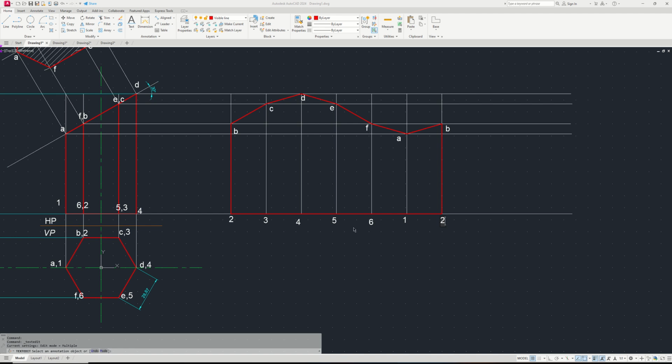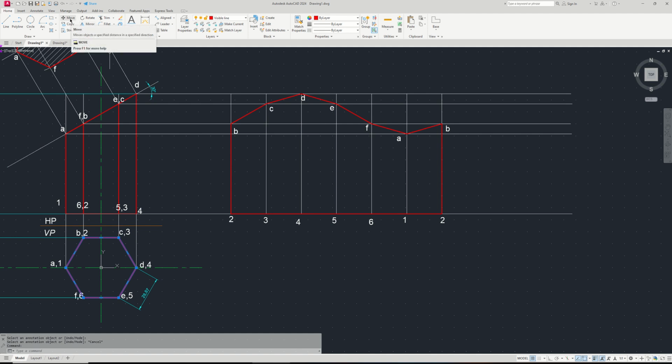Then I also made a correction of the names for the lower corners. Now what I'm going to do is to bring the top parts, the truncated part, and add it at the top. Then lastly, I'll bring the hexagon out at the bottom. Okay, easy thing I can do, select hexagon, then use the move command or copy.